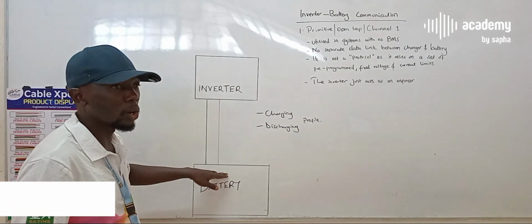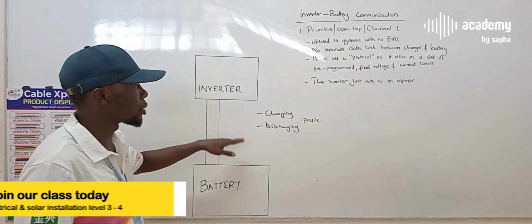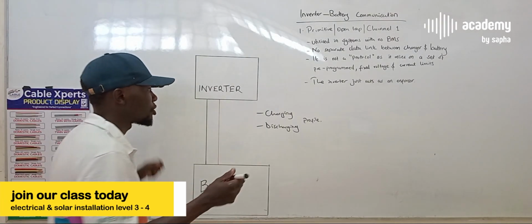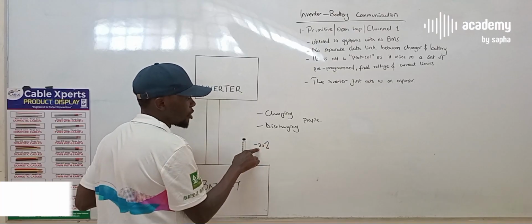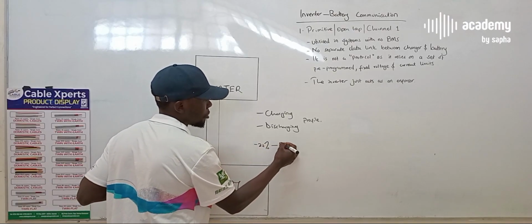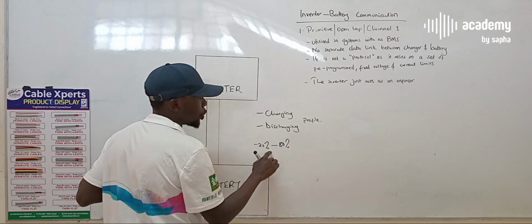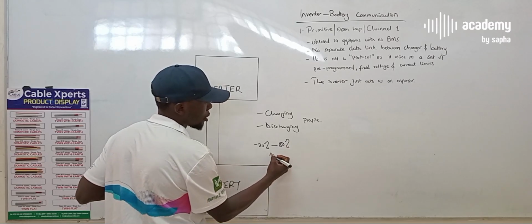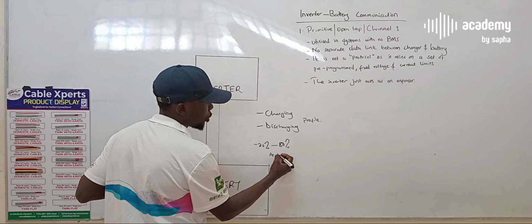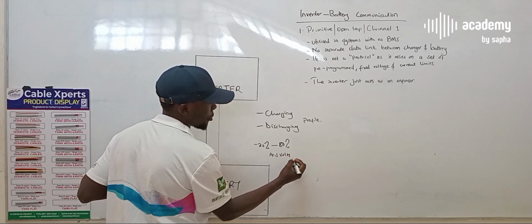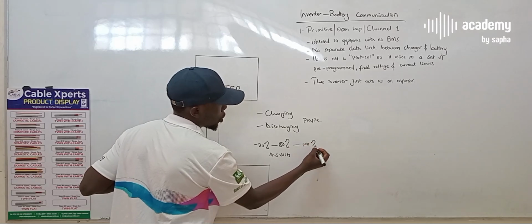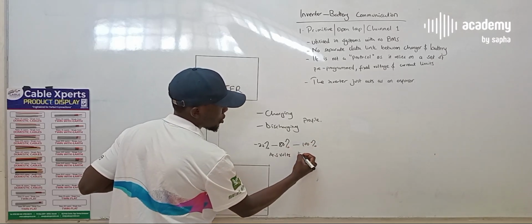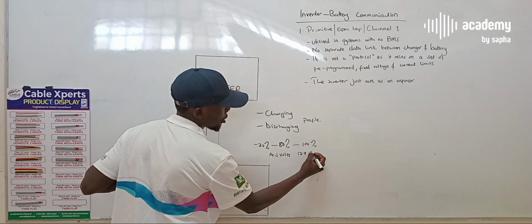or structure or architecture. So there are batteries where, for you to move them from 20% to, let's say, 80% state of charge, you need, let's say, 14.5 volts. This is just an example. Then from 80% to 100%, you'll be charging with, let's say, 13.8 volts.